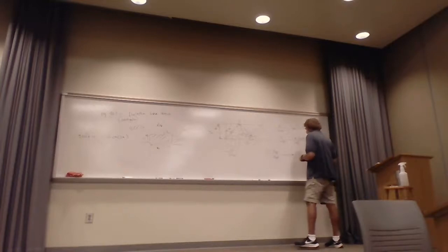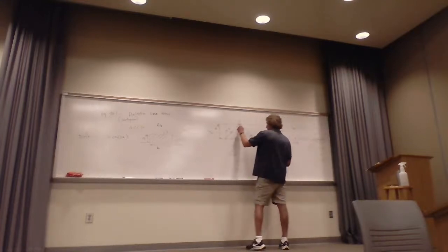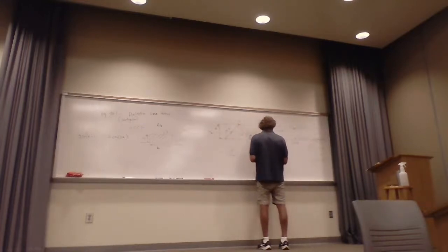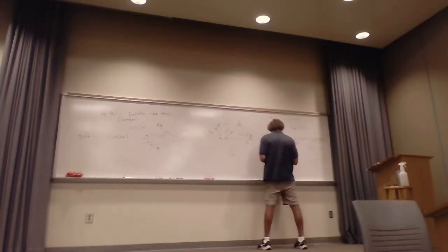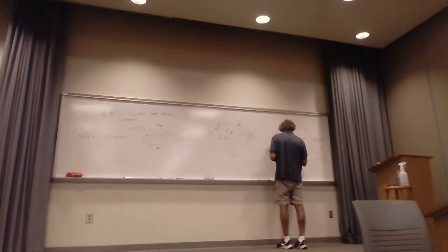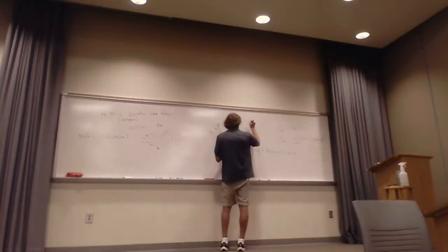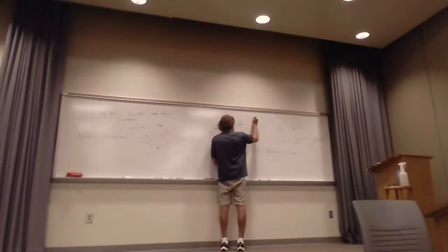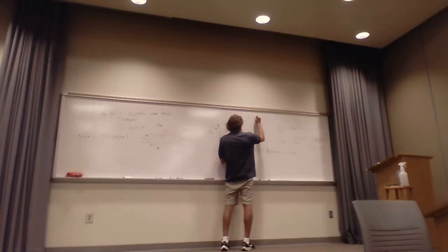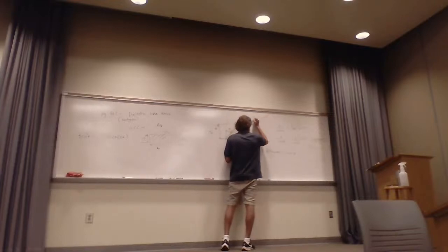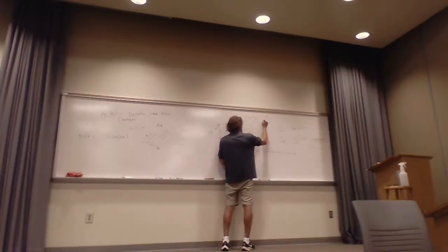Now, that's the distance traveled from here to here. And if I multiply that by beta, so beta in the core, or beta in the slab, times 2a cosine of theta incidence right there, has to be 2 pi m, where m is going to be an integer number. Now there's also 2 times the phase change that would be associated with the reflection coefficients right here and here. This is where it gets kind of a little hairy. So we know reflection coefficients could either be, we know we're going to have eta 2, eta 1 if we use the impedances, and then eta 2, eta 1.